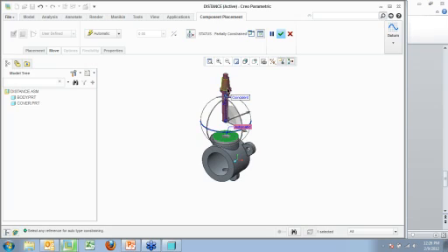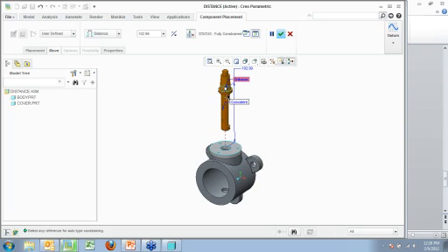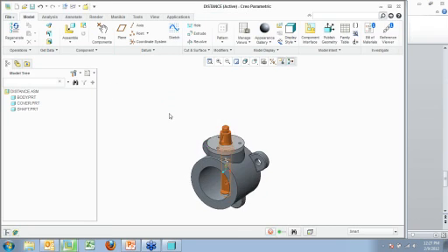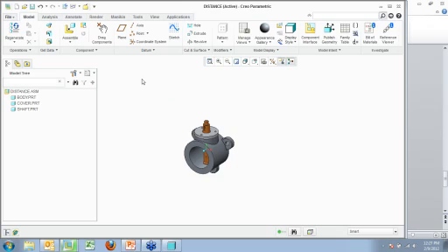So now let's go in and select this surface and that face, and drag it down here. Notice it turned orange, and this is purple to show me that my distance constraint is the one that I just constrained, the one I'm playing with. Notice that my dragger disappeared. It's fully constrained, turned orange, so that now I know that this part is 100% fully constrained. That should be down there. So that's really useful for making sure that you do get things 100% constrained.